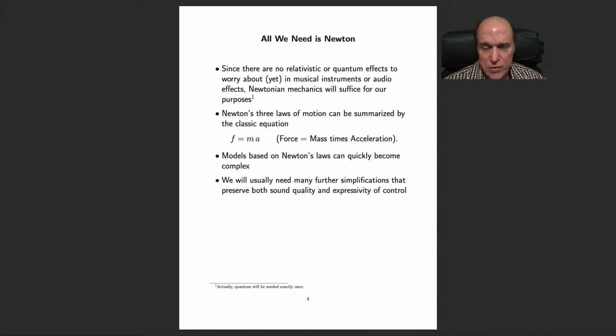And then we digitize those somehow. Because we have to implement everything on a computer nowadays, and so we will form difference equations, or finite difference schemes. So we'll find some way to essentially numerically integrate our differential equations through time in order to execute the behavior of the model. And so the forces will come in, and the differential equations will tell us what the system does, and then we'll extract an output, and that's our physical model output.